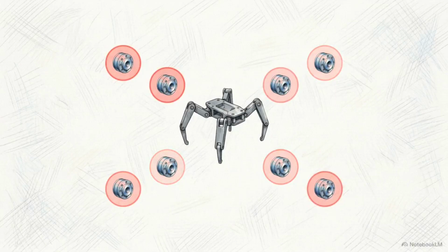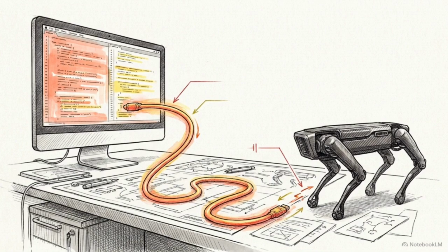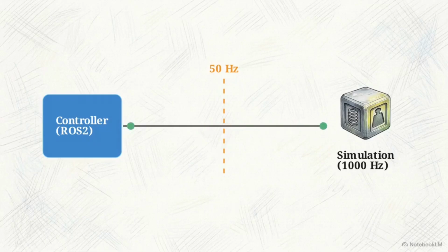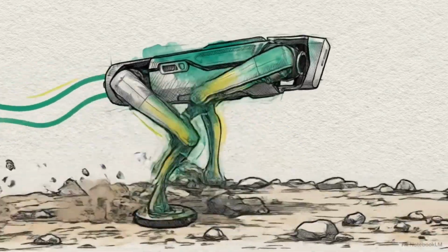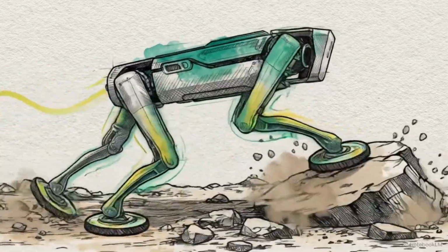To achieve stable movement, you must bypass the ROS2 messaging layer entirely and treat the robot as an integrated agent. Gazebo plugins provide the necessary interface. These are C++ classes that run within the simulator's own process, providing direct access to the physics and sensor data. Quadruped locomotion is rarely just a kinematics problem. It is a systems architecture problem that requires synchronous execution.